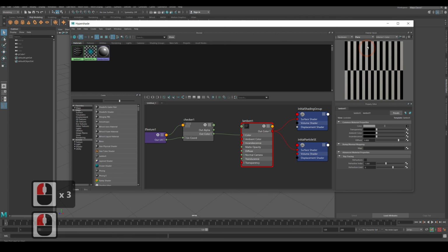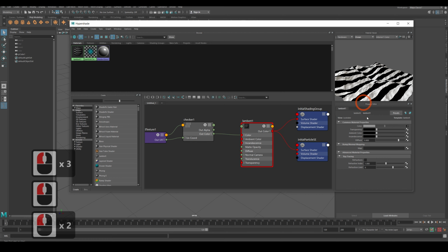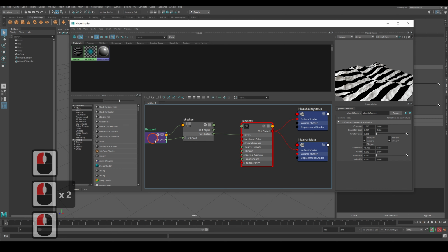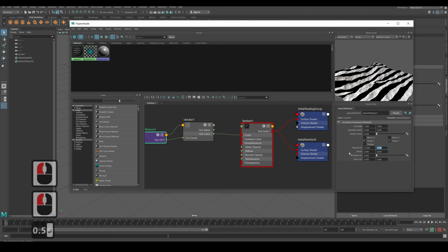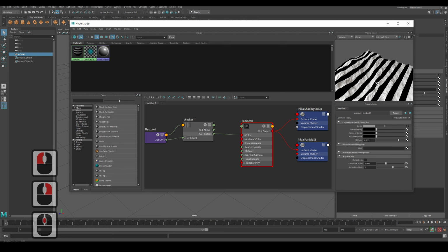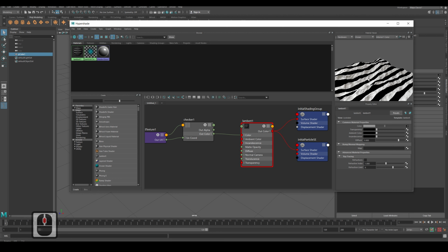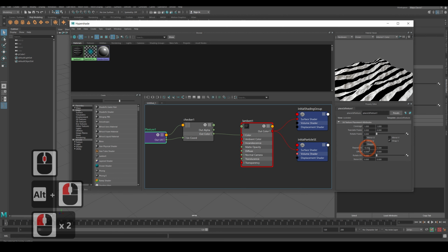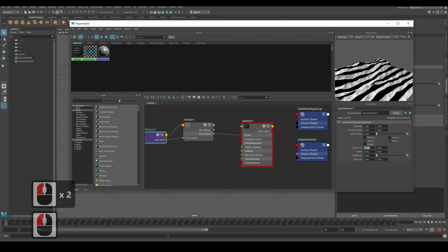We can use just some materials here, and you see here if I change this 10 to 1, it's like this. Let's try doing 10 to half. That's what we get. I forgot how to, oh yeah, Alt, and just the same way as we control the viewport, we control this one. So yeah, we can scale and repeat how many times our texture repeats in the model.